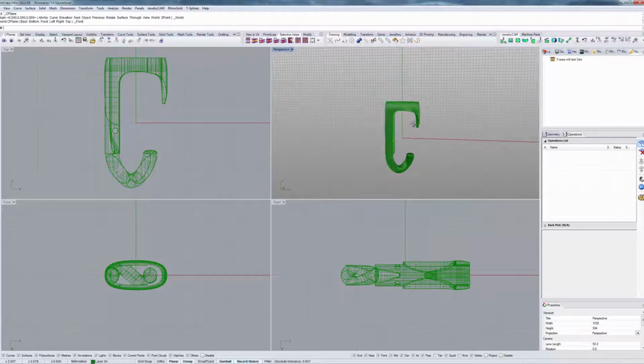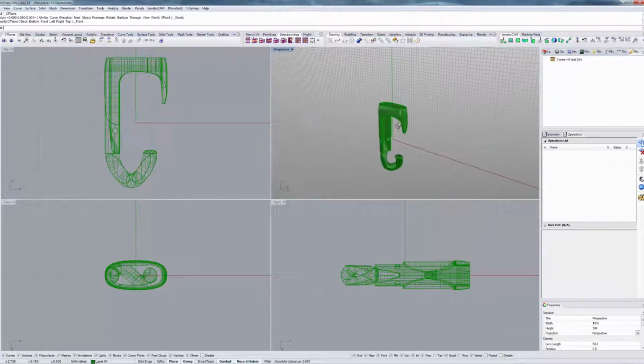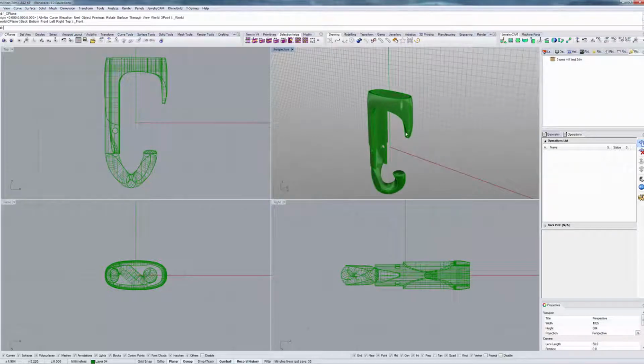The issue with this, of course, is that first of all, it requires manual work to position your construction planes, draw curves, and calculate multiple separate toolpaths. And moreover, as you may know from experience, any areas where the two toolpaths overlap, especially at curved angles like this, there'll be a bit of a mark where one area ends and the boundary of another one begins. No matter how calibrated or accurate your mill is, you'll still see a slight transition between these areas, which will then need to be cleaned up.